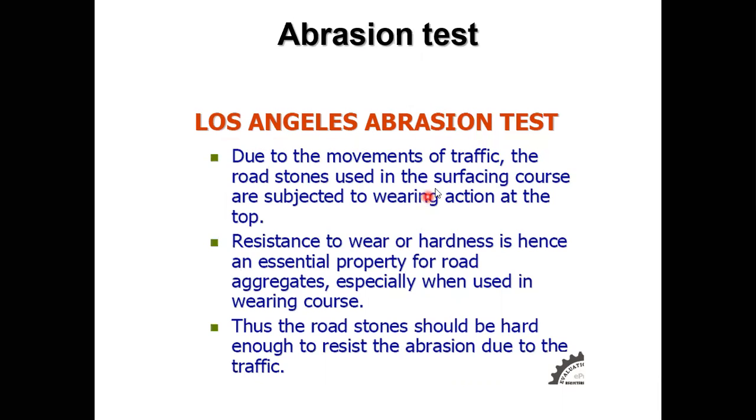See, due to the movements of traffic, the road stones used in the surface course are subjected to varying action at the top. Resistance to wear or hardness is hence an essential property for road aggregates, especially when used in wearing course. Thus, the road stones should be hard enough to resist the abrasion due to the traffic.